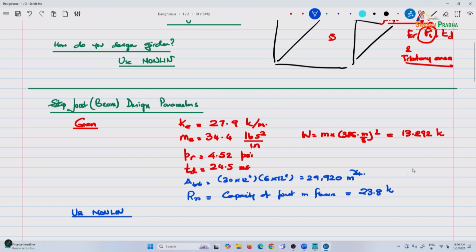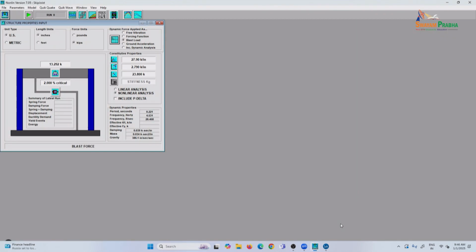Hopefully, they are all set. Yeah. So, can you see that, or I don't know. So, anyway, one thing I wanted to mention here was the value we have been inputting as 0.02 for damping, but it is 2. It is percentage itself, the input should be there.